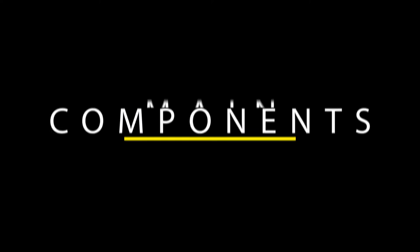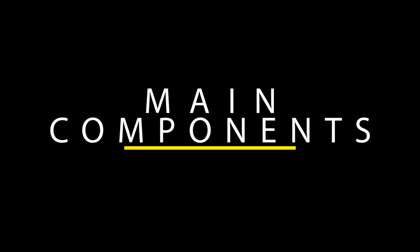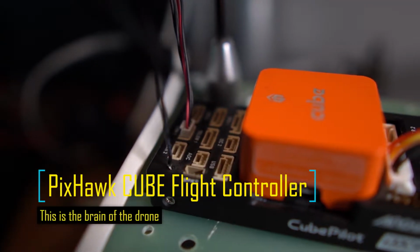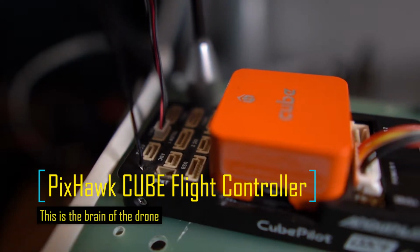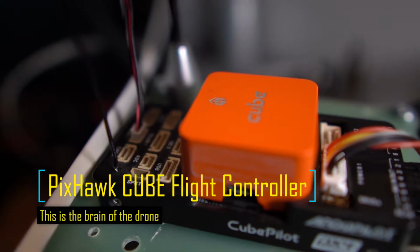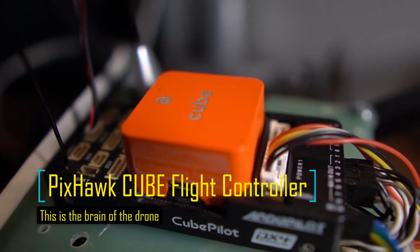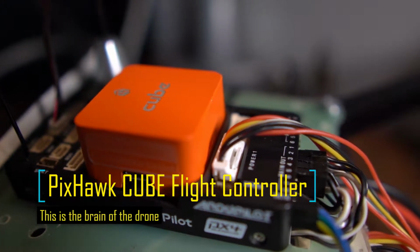Once the drone has been modeled in 3D space, now it's time to get to building the real thing. Here's a quick list of the main items I used to build this drone. The flight controller is the brain of the drone and is responsible for communicating with each individual component. It also has an ADS-B receiver to be able to route its path around existing air traffic in the area.